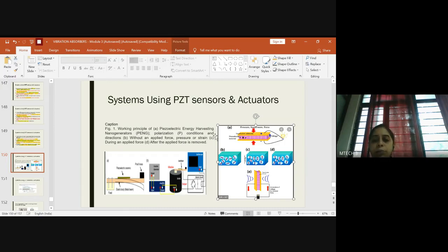If you have a smart road, a normal road is not called a smart structure. When you call a road a smart road, you have a piezoelectric patch beneath the road, and other connectivity with respect to technologies and a closed loop or open loop structure. Then you call that a smart road. If you have developed a smart road, and vehicles move on it, every vehicle will put a huge amount of load on it. When a huge amount of load is subjected at different points of the smart road, and you have a PZT layer below, that load will be converted into an electrical signal.